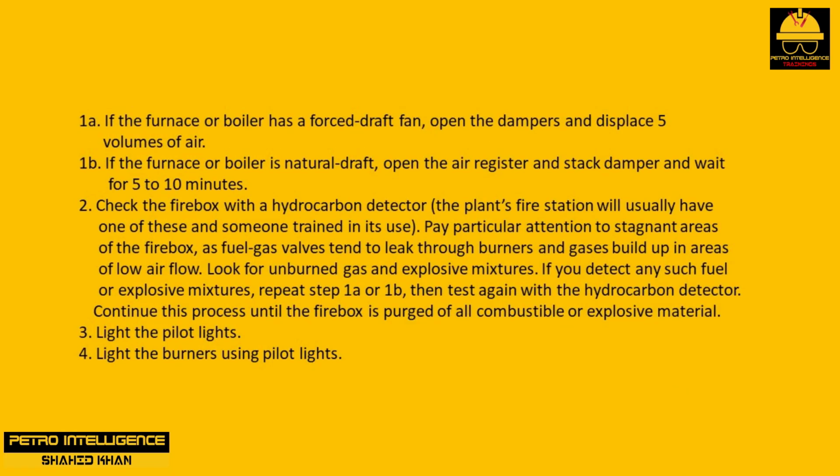1A. If the furnace or boiler has a forced draft fan, open the dampers and displace 5 volumes of air. 1B. If the furnace or boiler is natural draft, open the air register and stack damper and wait for 5 to 10 minutes. 2. Check the firebox with a hydrocarbon detector. The plant's fire station will usually have one of these and someone trained in its use.